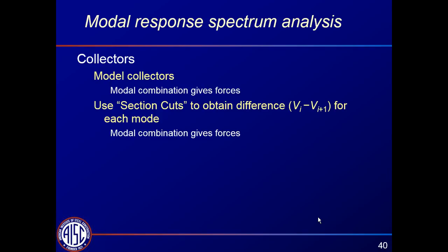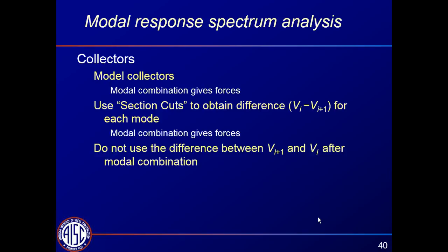As a reminder, any quantity of interest in a modal response spectrum analysis really has to be tracked mode by mode. You can't use the difference between maximum combinations in a modal response spectrum analysis. That is mathematically meaningless, and for design purposes meaningless as well.